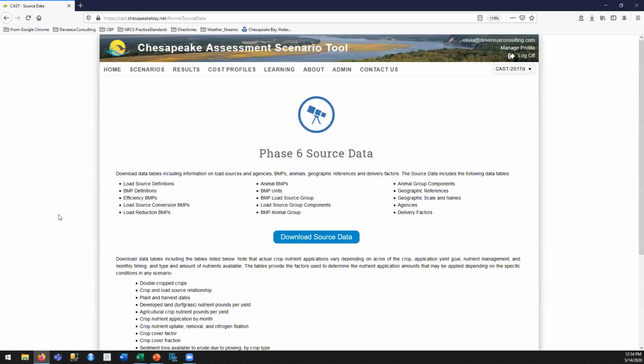Let me pause here and go back to these questions. I see a number have come in. One of them is if stream restoration benefits are independent of the work being done off channel. So if you've got several practices on a site, you want to put in that you've done your stream restoration. If you've also put in some other BMPs, you do want to add those to your scenario as well. So you do want to add the independent BMPs.